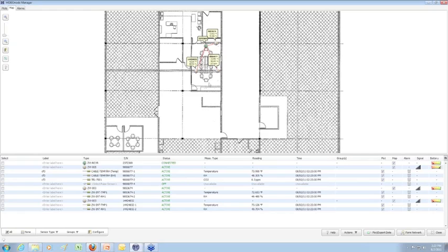So as you can see, you can start to position this, and it gives it more of a realistic appearance here. There was a question earlier in terms of if you need to change parameters, do you need to be plugged into this? No, you don't. The information gets sent downstream, as you saw as we brought the CO2 sensor on. It may take a minute or two, and sometimes if you're down a couple routers, it may take a bit to get that information down there. But you can configure these and change everything wirelessly just from sitting at your PC, and the information will get